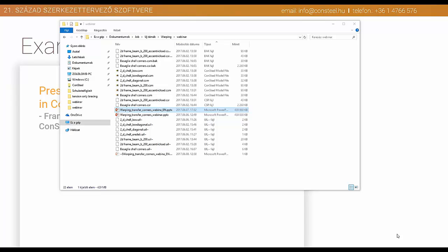In order to physically execute the definition, I go to Frame Corner Wizard, and you can see this new window which was already shown in my presentation. There is a toggle switch at the bottom where you can switch off the definition of any sort of connection. If I switch off, then there will be no corner applied of any kind.